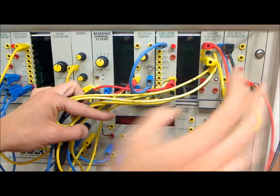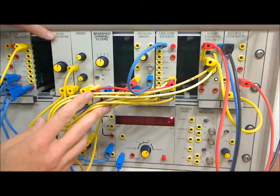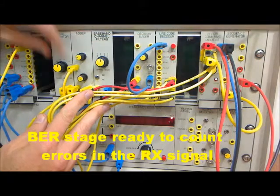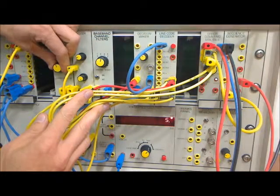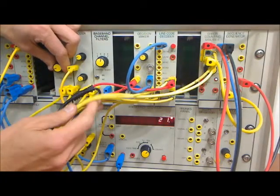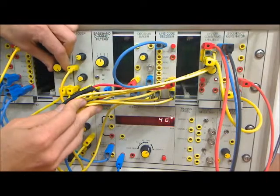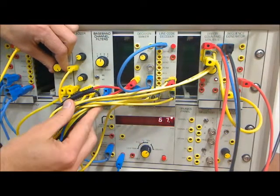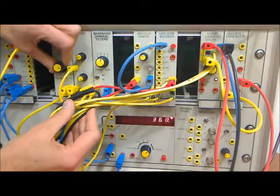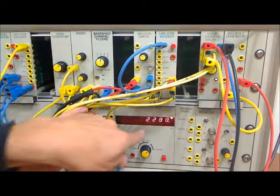So now that it's all lined up, our bit error rate instrumentation system is ready to count errors created by the noise in the channel. Okay, here's the noise generator. We've adjusted our levels at the adder. As I start to increase the noise incrementally from a very minimal level, you'll start to see small amounts of errors accumulating bit by bit. Now, as we get up to 14 dB, errors are starting to accumulate. The more noise in the system, the more errors that accumulate, until we dial up to a maximum level of noise.